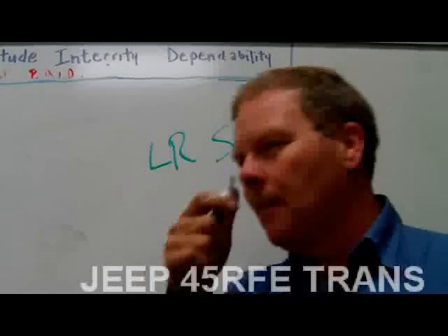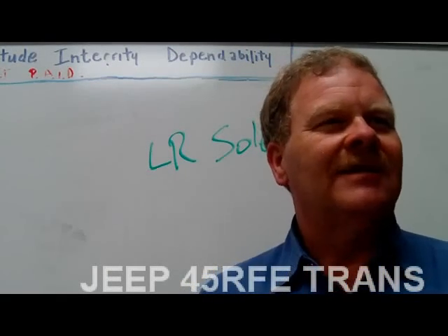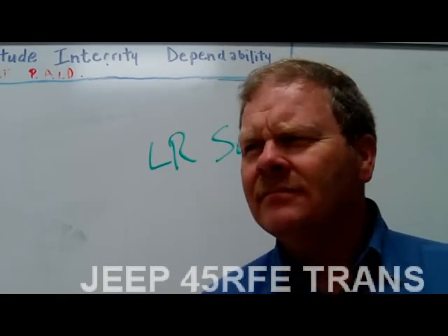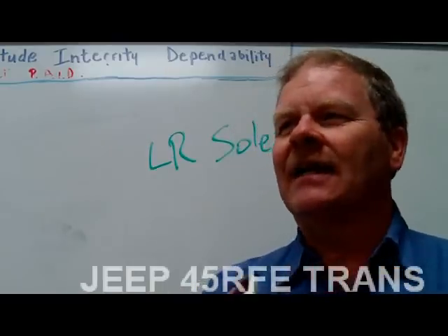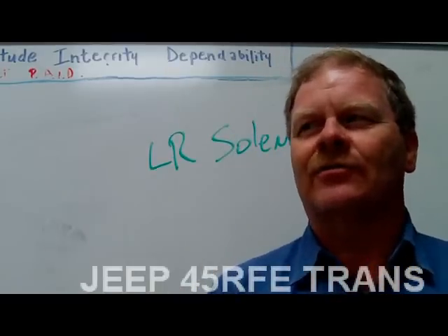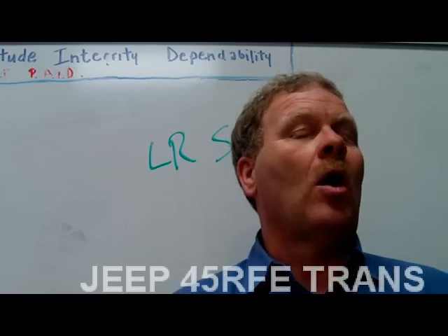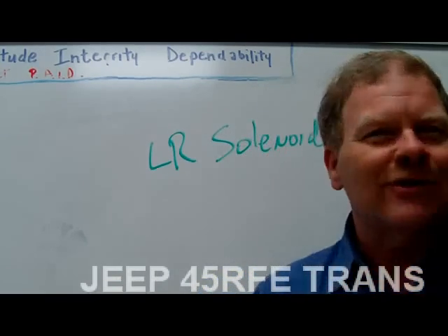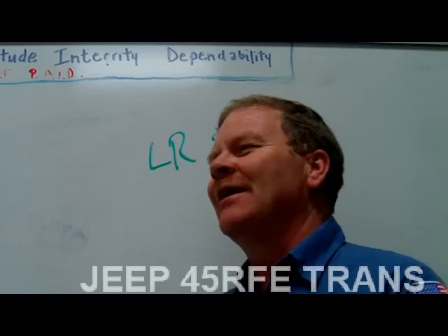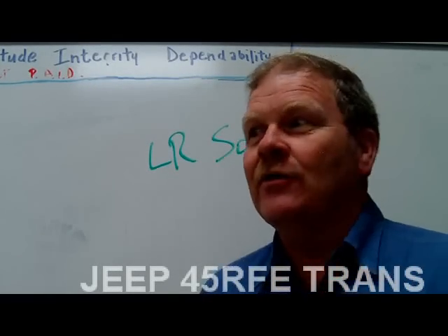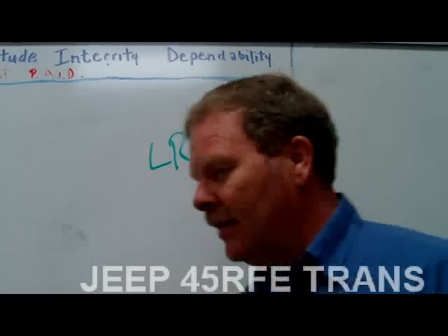Now what are you thinking? I'm thinking left, right solenoid. Left rear. Oh, left rear solenoid. Yeah, that's exactly what the people that typed the thing for Genesis were thinking. It was low reverse, and in a transmission, not left rear. It's confusing, I know, because they use LR.